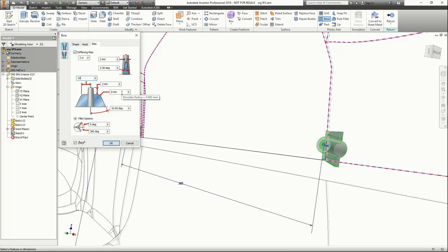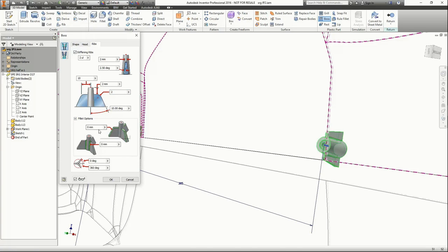1 or 2, so a couple. Yeah, so what happens with plastic is if you have the mounting mechanisms onto the plastic as the plastic flows into it, it creates, best way I can call it, an anomaly. It doesn't fill perfectly on the back side, and then you'll get a little wiggle into the shape itself.